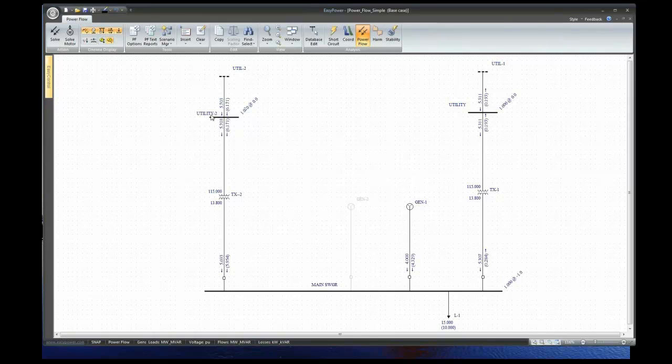So now I'm balancing this out because where these connect to this bus, those two voltages have to be the same. So I have more voltage drop across this transformer than I do this transformer. That's where I'm asking for 2% more voltage here than here, and here's how it happens, right across this transformer, because of the additional VAR flow. Okay, so the VAR flow is almost totally determined by the voltage.